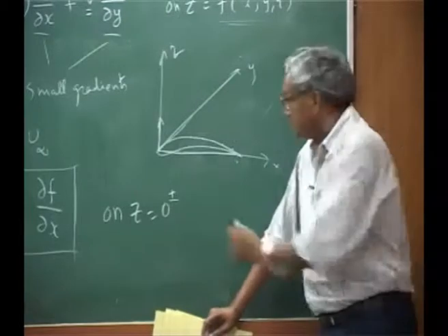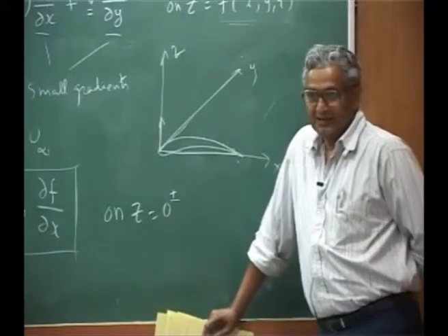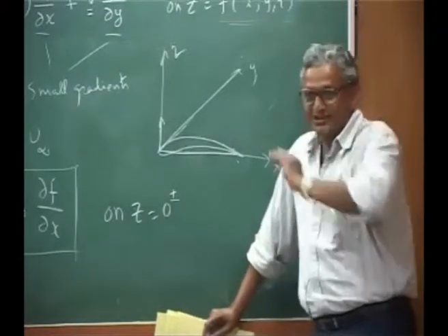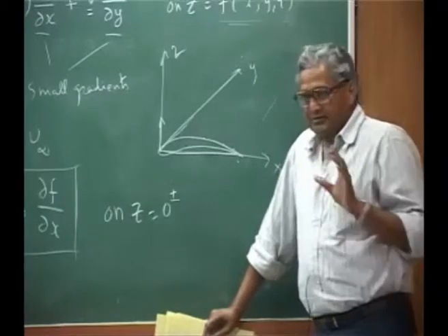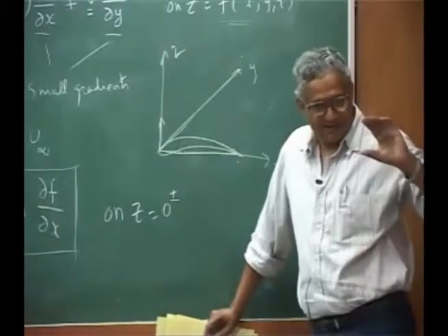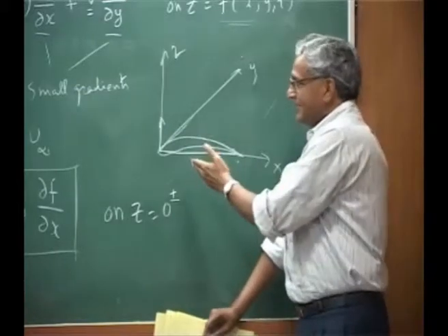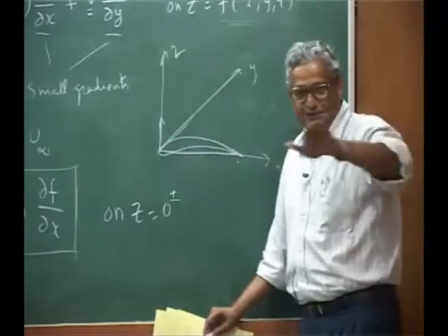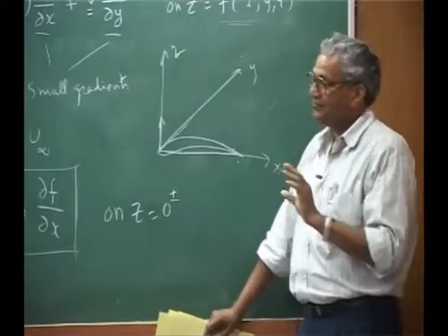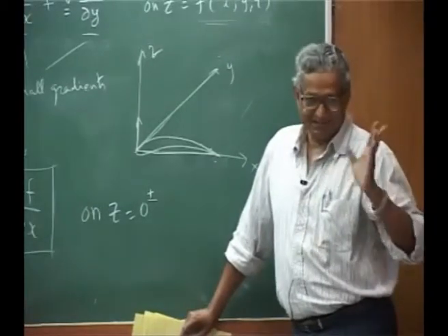Then you may ask, what happens to the thickness of this? Okay. That is why you have to do one approximation, later we will go to that. The assumption we made is these surfaces are thin, and the slopes, whatever the aerofoil shape which you make, the slopes are also very small. Therefore, we have neglected the higher order terms, that is the nonlinear terms.